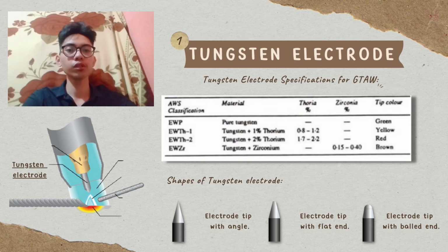As you can see on the table, tungsten electrodes are classified into four types and are identified by color code. Based upon observation, it shows that a pure tungsten electrode has a lower current carrying capacity with AC, and is rather more prone to contamination. Compared with pure tungsten electrodes, thoriated tungsten electrodes have higher current carrying capacity and better electron emissivity, longer life, greater resistance to contamination, meaning it has easy arc initiation and better arc stability.